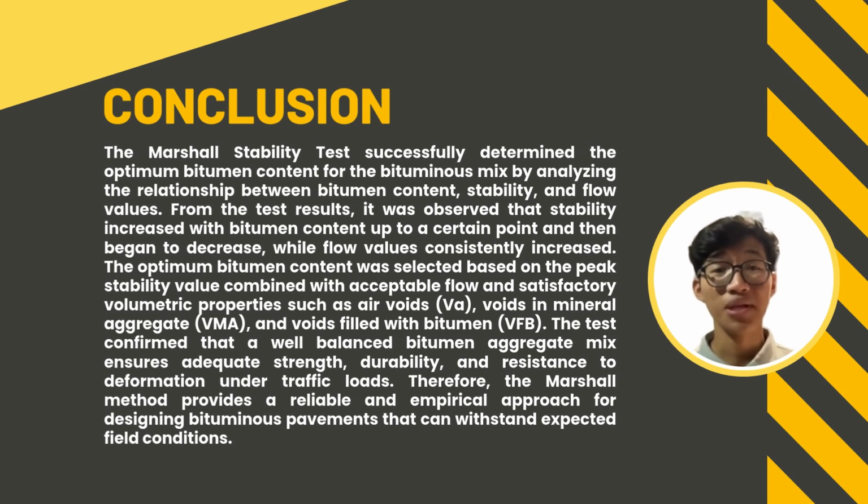The optimum bitumen content was selected based on the peak stability value combined with acceptable flow and satisfactory volumetric properties such as air voids VA, voids in mineral aggregate VMA, and voids filled with bitumen VFB. The test confirmed that a well-balanced bitumen aggregate mix ensures adequate strength, durability, and resistance to deformation under traffic loads. Therefore, the Marshall method provides a reliable and empirical approach for designing bituminous pavement that can withstand expected field conditions.